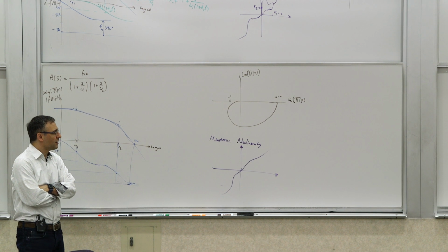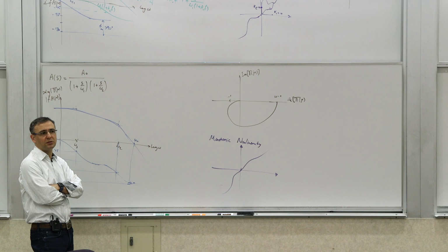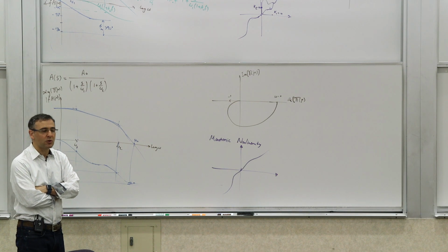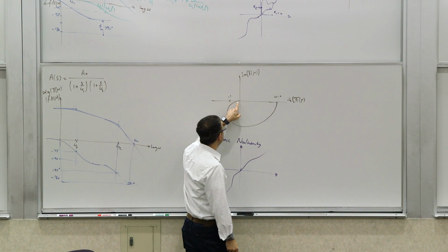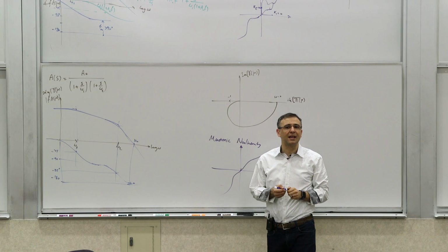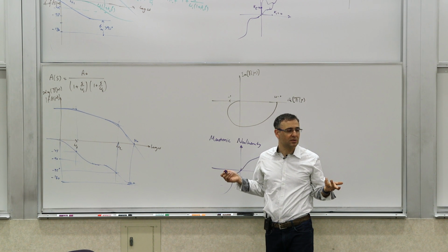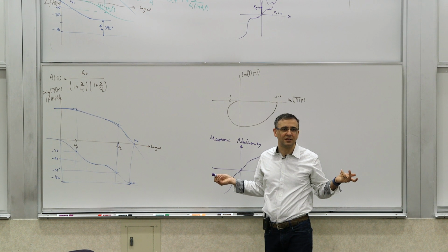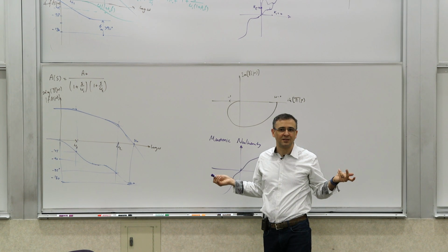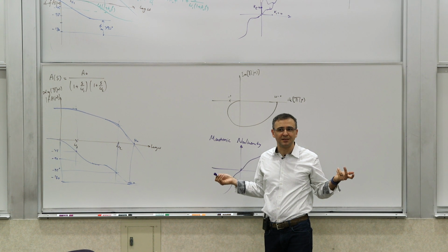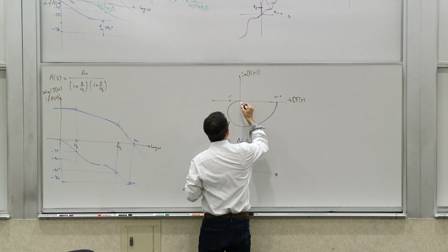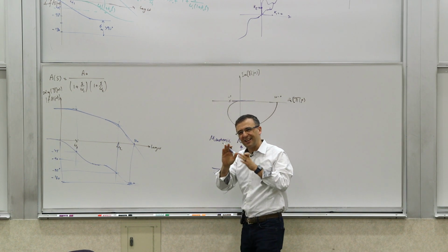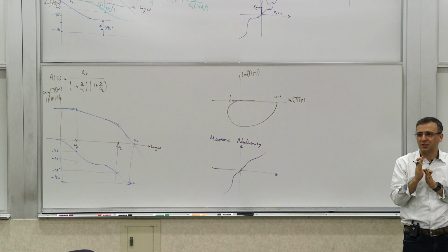In the case of a monotonic nonlinearity, if you have K1 and K2 that are 0 and infinity, it means one of the points is at infinity, the other point is at 0. The question is, can you find a line that passes through point 0 and is not crossed by this? You kind of can, if you think about it. It appears, well, marginally. So maybe this is the line. You're on the verge of this being possible.